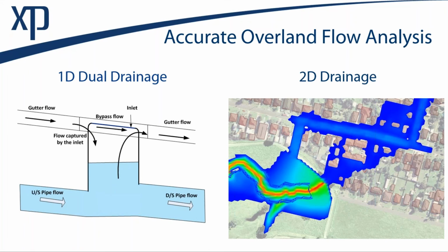But again, this is incredibly tedious to do, and there are huge limitations to this. Mostly this was used for modeling flow in streets between surcharging manholes. It's not realistic when high flood conditions exist and flooding extends beyond the streets. Once it overbanks the curb, or flows into a ditch that diverts away from the street, then we've lost any way to accurately capture what happens to that flow.